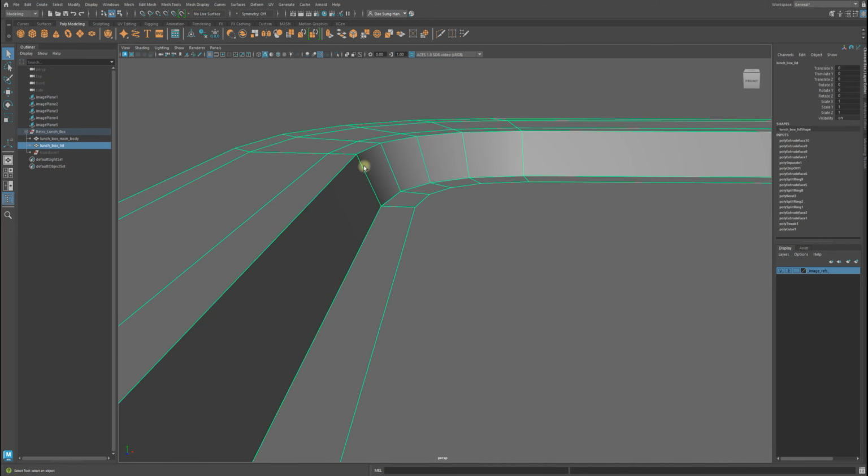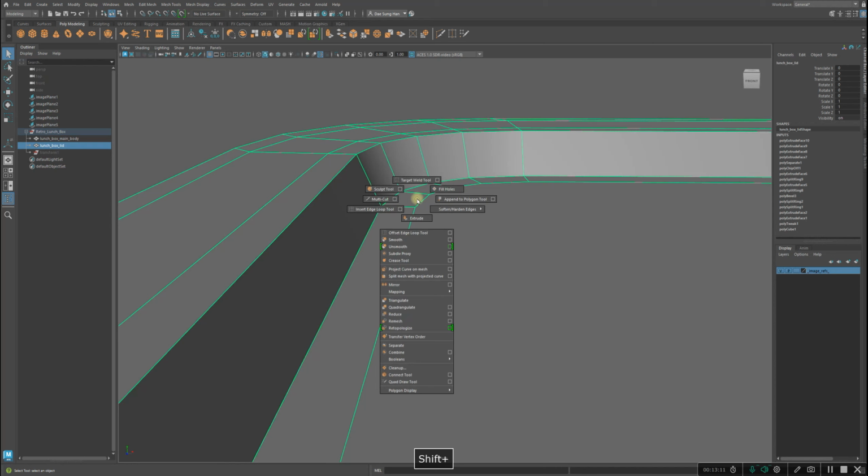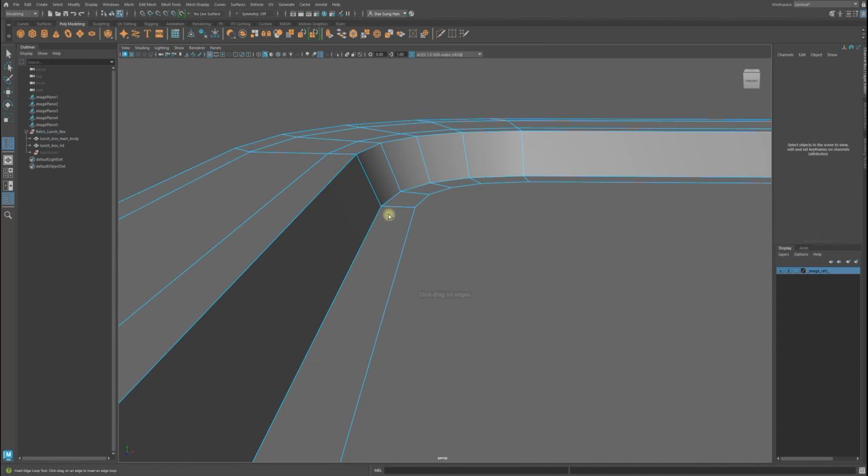But let's say I want it more rigid. So I'm going to shift, right click and hold, insert edge loop, right? Previously we used extrusion. Now I'm going to go back to insert edge loop. And I have the line tool activated. So rule of three, one section here, right? And one here. Watch, and it doesn't always have to be a certain way. Like I could just put one right here, and look what that will do for us.